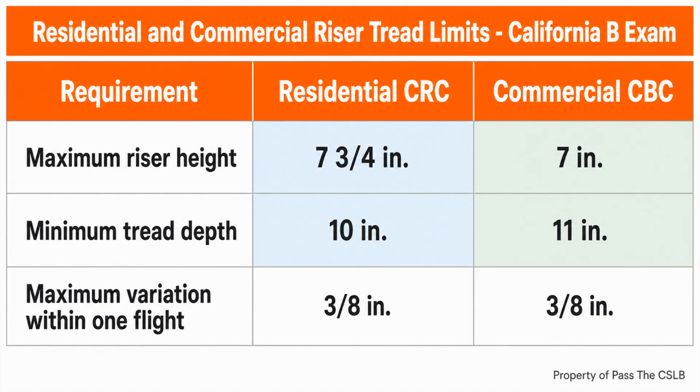materials were added. I want you to separate 3 questions every time you inspect or supervise stairs. First, what code environment controls this stair? Residential, commercial, or temporary construction access? Second, what triggers the safety component? The number of risers or the height of the open drop? Third, did the finished materials preserve the intended geometry? Those distinctions keep similar numbers from getting mixed together.